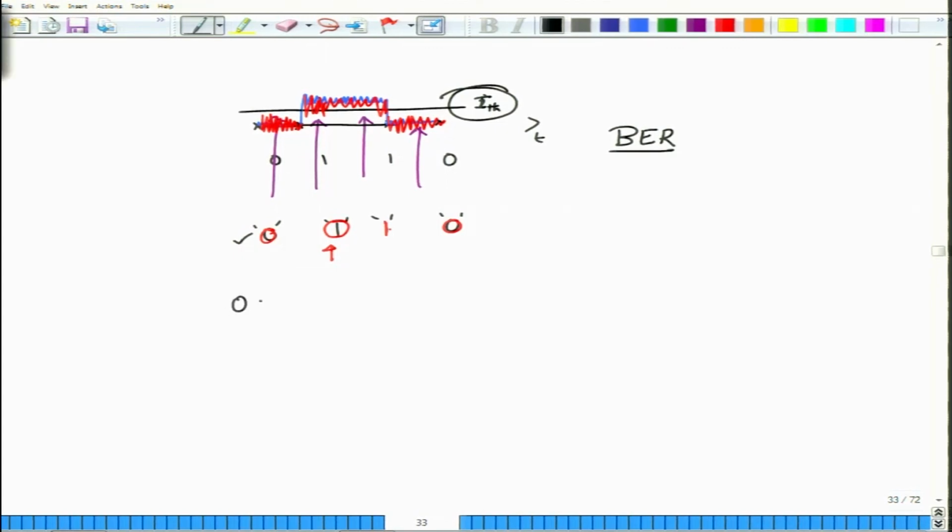Now, we have said that when you receive a bit 0, the total noise variance, which we will call sigma 0 square, will be given by 4 kT by RL times BE. Clearly, I am neglecting the shot noise contribution from the power P0 because I am assuming P0 itself is quite small. And then the noise variance when you transmit a bit 1 will be denoted by sigma 1. That would be, in addition to this 4kT by RL BE, there will also be 2q I1 average times BE, I1 average standing for the average photocurrent that we have received, BE being the bandwidth that we are considering.